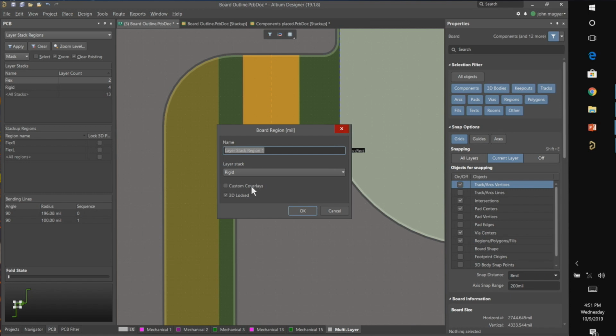Stiffeners, things like stiffener, that's more of a challenge. We hear that a lot. Do you support stiffeners for flex? You can have two dielectrics together. You put one as an adhesive and one as your stiffener piece. Two dielectric layers in your stack up. The one thing, we don't have a way currently to show an outline of a stiffener and then have its material and everything.